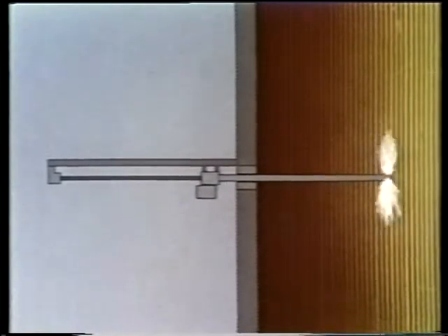Retractable soot blowers can be described according to the length of their element and how far they extend into the boiler. Short tube retractable soot blowers are often called wall blowers. They go into the boiler only far enough to blow soot off the boiler's tube wall. Long tube retractable soot blowers, on the other hand, extend as much as 30 feet or even more into the boiler. These are used where short tube blowers can't cover enough of the area and where fixed or rotating stationary blowers can't be used because of the high temperatures.